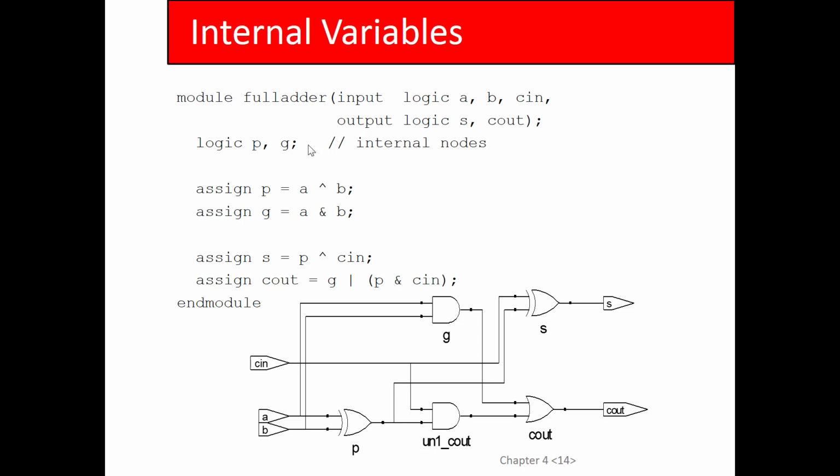So notice the syntax here. This is a Boolean and, ampersand; Boolean XOR is a caret; Boolean OR is a bar. You can use parentheses in there. So what's going on here? We've looked at full adders before. They didn't work like this. Well, the reason they did it this way is that there's a style of adder. You know ripple carry adders, right? There's a style called a carry look-ahead adder, which is a vastly faster version of an adder, but it requires a lot more logic, so that's the trade-off.